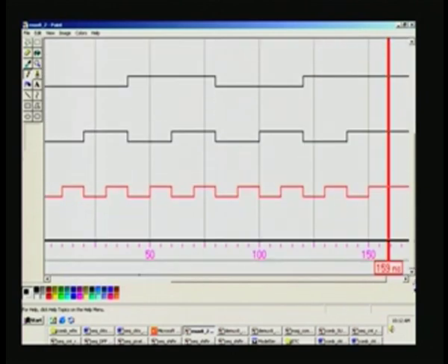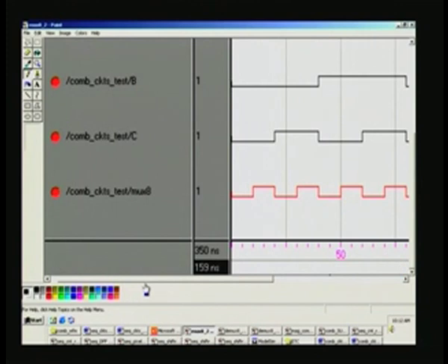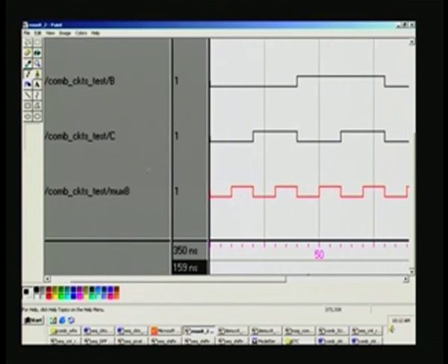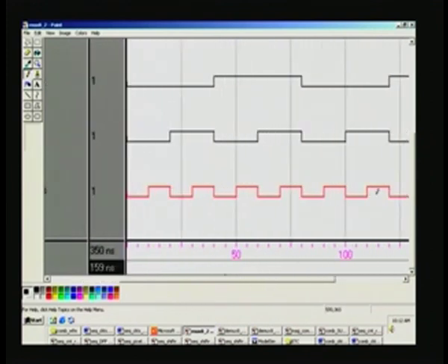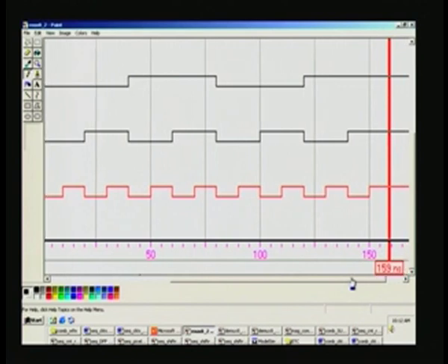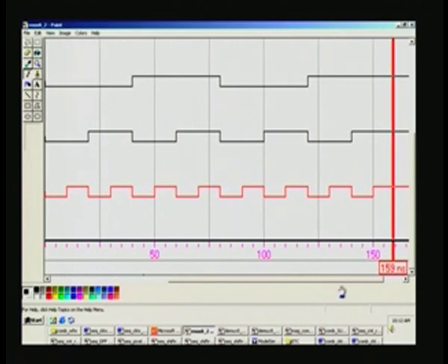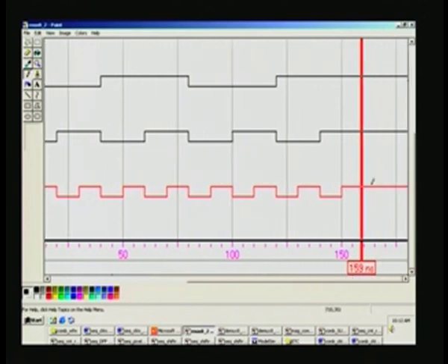Finally we had this waveform, which is the mux side, and the corresponding inputs, this is I0, I1, and since ABC keeps on varying in the binary fashion that you have already seen, you have 3, 6 here and 7 here, and the 8th one is here because I forgot to deactivate. Of course, that is immaterial, and so you have a total of 8 inputs corresponding to I0 through I7.